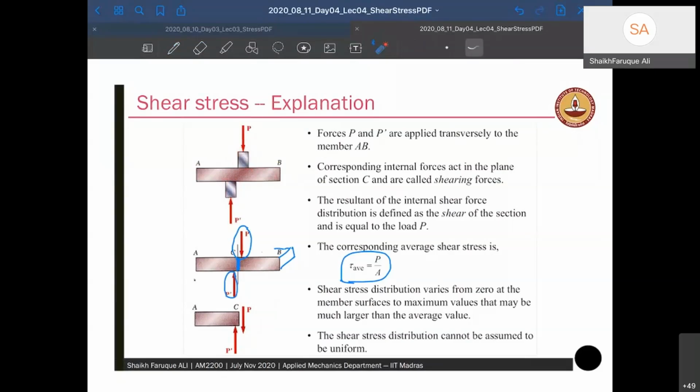They are on the same cross-sectional line. What will happen if you make them a little sharper here and sharper there? Let's say it's a sharp edge here and the other one is a sharp edge here. The rod will start tearing from this point, right?